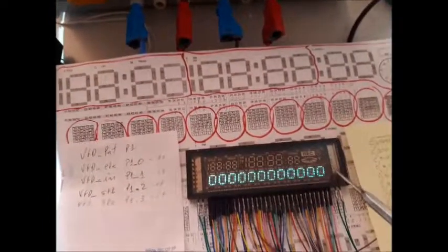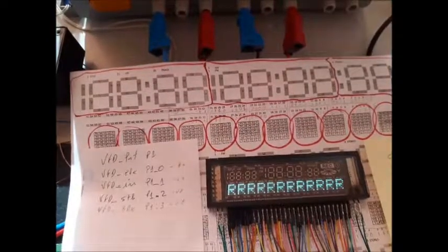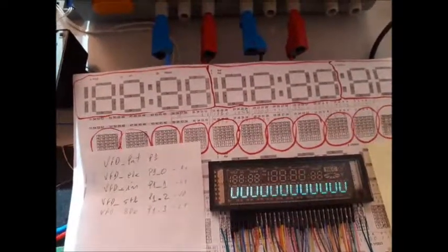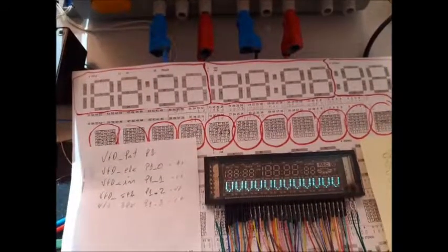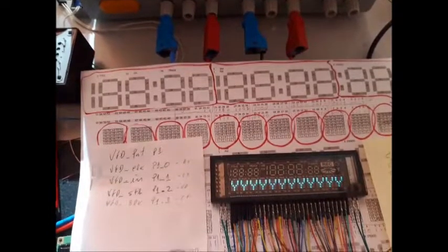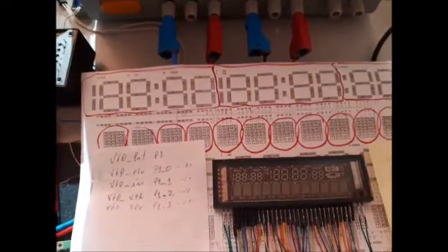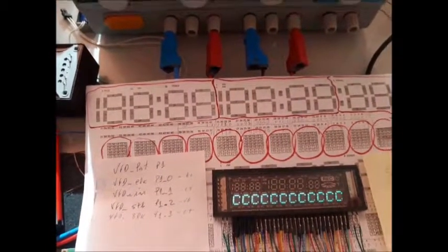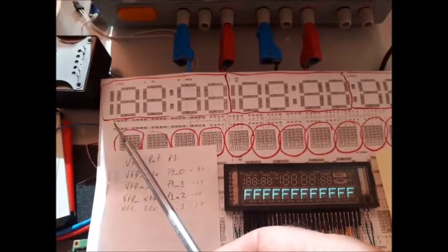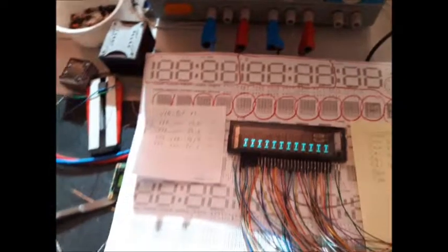The filament pins are not included, okay, they are not important for the control of the remaining parts. For this reason, I need to use 7 ICs, multiplied by 8 pins. You have a total of 56, but I only have 55 pins to connect here. Okay, one is remaining free.